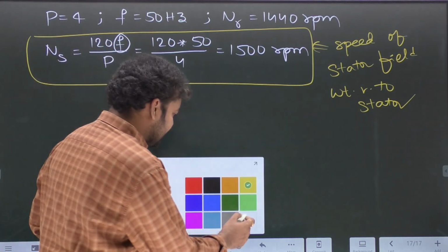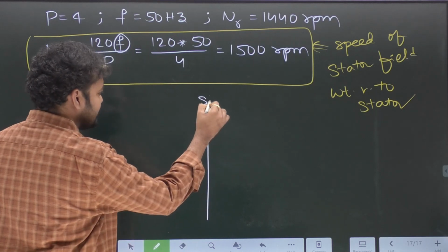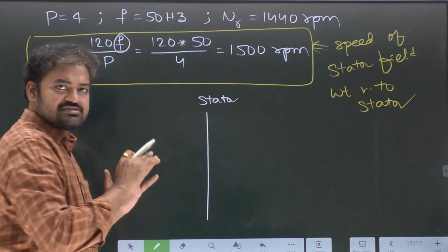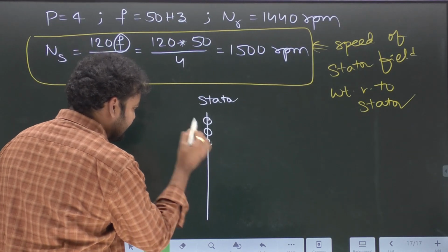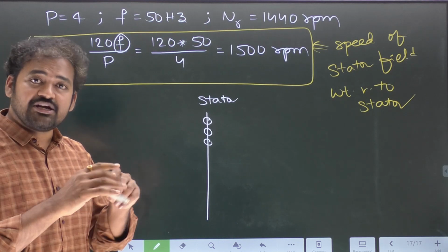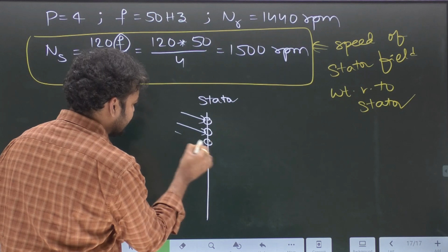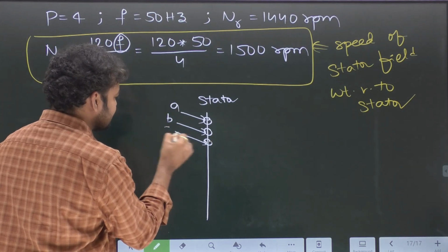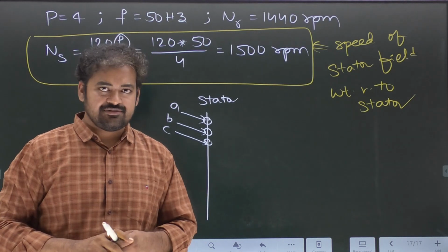Okay. So let's take a stationary line now first. This is the stator part. Stator is always stationary, and we have a 3-phase stator winding here. Important thing is, is the stator winding a closed circuit, or is the stator winding excited? Yes, supply was given to the stator winding, ABC sequence. Remember, when nothing is given, by default the sequence is ABC.